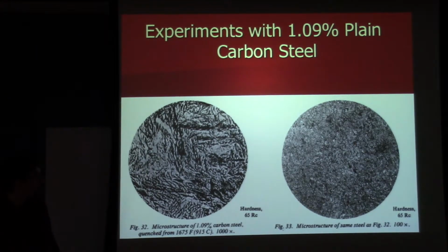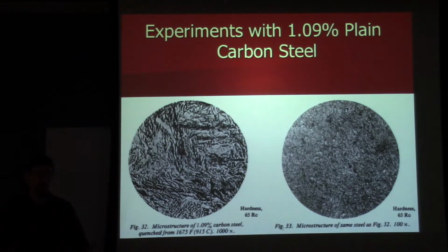So what that really tells us is that microstructure and hardness go hand in hand. And of course, hardness, we also know, is directly related to other mechanical properties. So the takeaway, one of many, is that microstructure is directly responsible for the properties that you get out of a piece of steel. So controlling the microstructure now becomes the job of the metallurgist to get the properties that the customer wants.